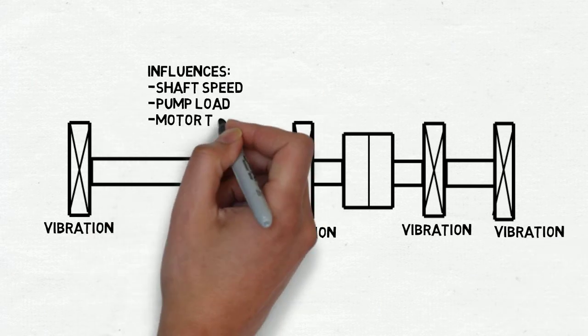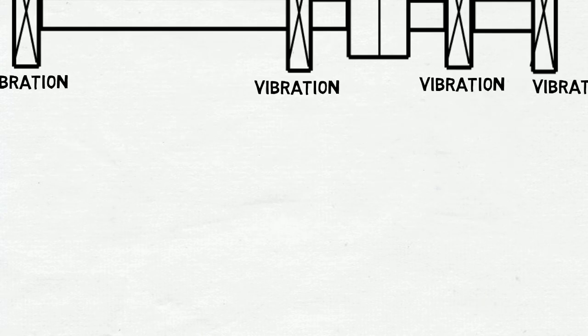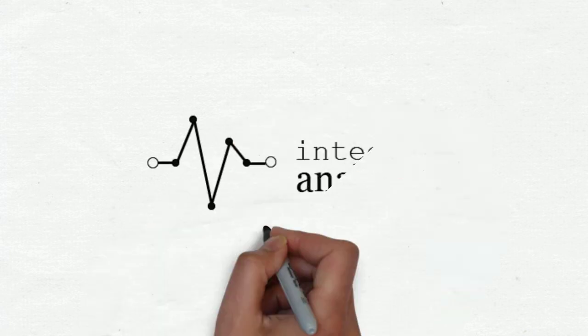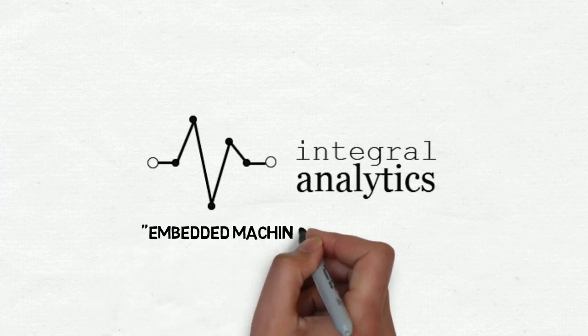influence variables. More complex models are often available to monitor, such as creating a detailed vibration model with additional features such as phase angle, particularly for proximity probe type of sensors, calculating motor efficiency, and monitoring motor current signature analysis. However, these basic models will get you started and are likely what you already have for instrumentation availability.